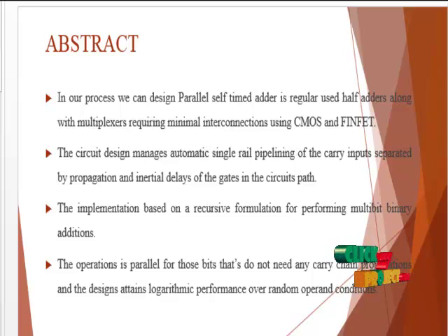On the other hand, the completion in the proposed adder uses so-called logic and early completion, selecting the proper response instead of a fixed number of delay lines. The logic implementation is of high fan-in and recommends delay-insensitive adders using dual rail encodings. These asynchronous adders assert the timing constraints of operations. To operate correctly, they assume bounded, unknown gate and wire delays. This is the delay variation of the DI adders in the DI ripple carry adders.